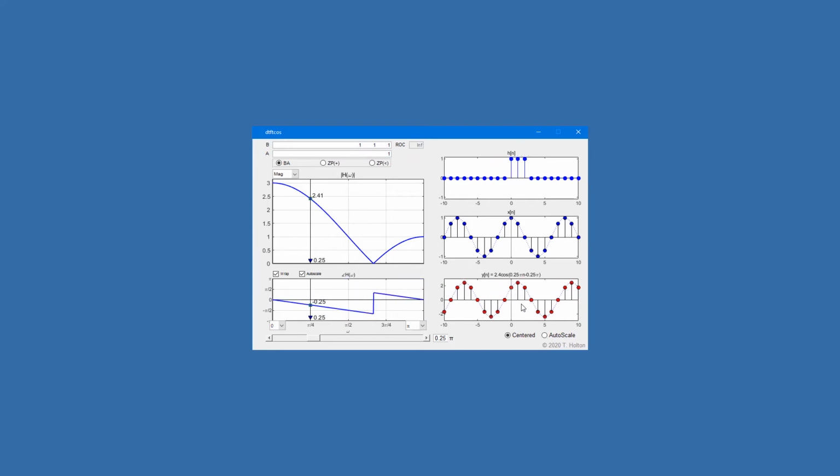the output change appropriately. By selecting the autoscale control, you normalize this bottom trace to full scale so that when you change the frequency, you can show that for a linear phase system, you always get the same time delay.